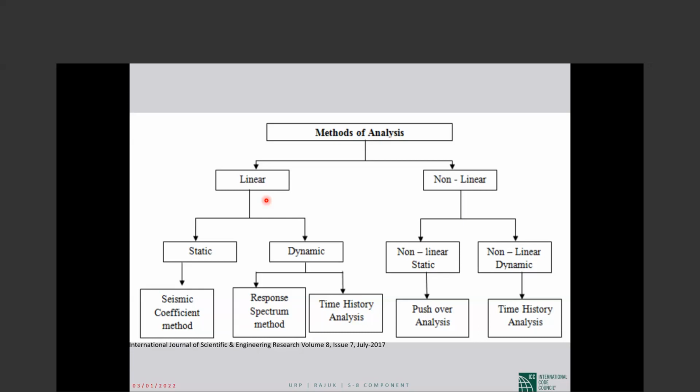Capacity is simple for force control, for the scary ones, for the brittle ones. For them, we just look at their strength. We don't want to check their plastic behavior, for example, because we don't want them to go through that range of behavior. If they pass the strength limit, then they are gone.